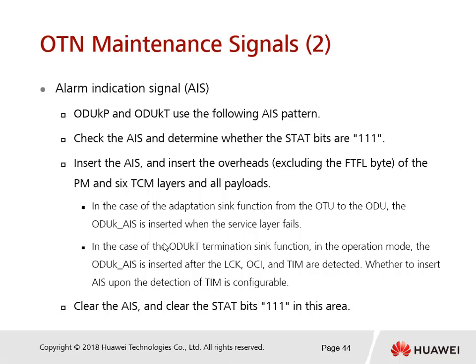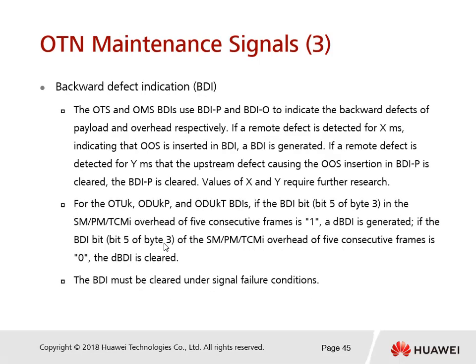Whether to insert AIS upon the detection of TIM is configurable. If you want to clear the AIS, we should make sure the status bits are 111, and clear it first.